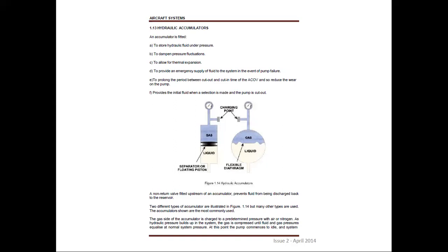They also term them as hydraulic charge accumulators. They maintain pressure so that in case you need to operate the system without power from the aircraft or the engines, you can still use the system.